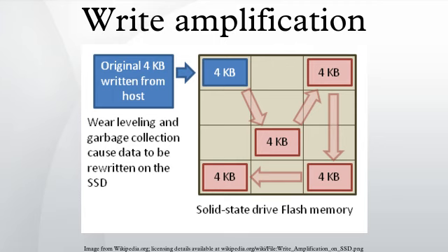When new data comes in replacing older data already written, the SSD controller will write the new data in a new location and update the logical mapping to point to the new physical location. The data in the old location is no longer valid, and will need to be erased before the location can be written again. Flash memory can only be programmed and erased a limited number of times.